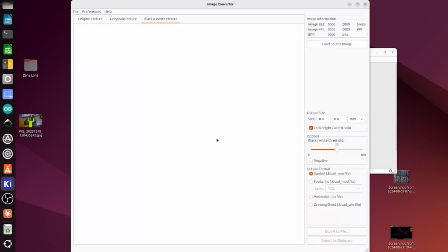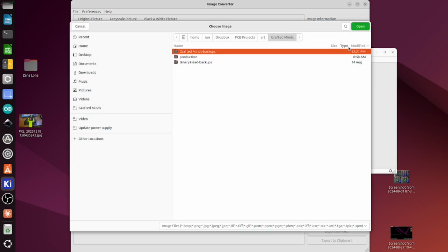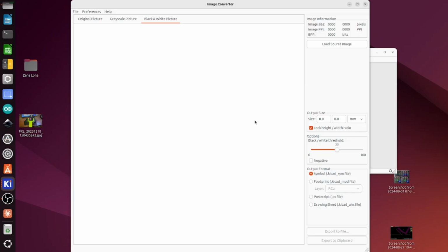This image converter, this is kind of cool. Like I said, I'm an Easy EDA convert, and converting images was not something that Easy EDA did so well. Most of the images that I would want to import are in a vector, which there's a different way to do through the board editor, which I'll show you in another video another day. But if it's not a vector graphic, this is a great way to import a JPEG or a different kind of image. I'm not sure which formats this works with, to be honest, but I think you've got a lot more controls here over how the picture comes out looking on the board in whatever layer you put it in. So, handy tool.